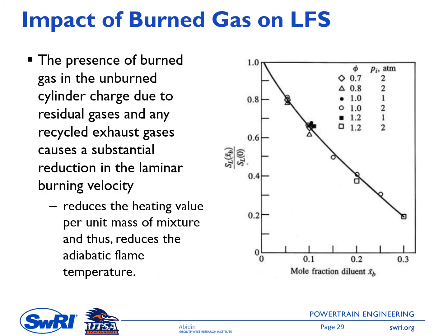The laminar flame speed is strongly dependent on the temperature, so increasing temperature increases the laminar flame speed. Pressure has a minor impact on the laminar flame speed. And you saw on the previous slide that the laminar flame speed is also strongly dependent on the equivalence ratio. So the laminar flame speed is maximum at phi around 1.1.